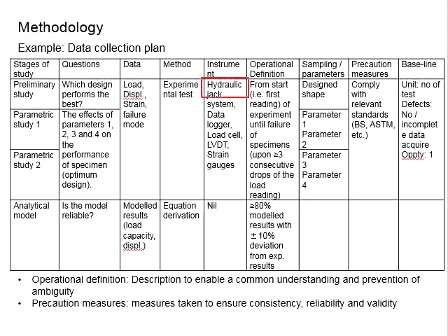You will need a hydraulic jack in order to impose load onto the specimen. You will need a data logger for you to monitor and store the data. You will need a load cell for you to measure the load. You will need an LVDT for you to measure the displacement. And you will need a strain gauge for you to measure the strain in the reinforcement bars. You might also need a camera for you to take snapshots in order to show the failure modes of the specimen.